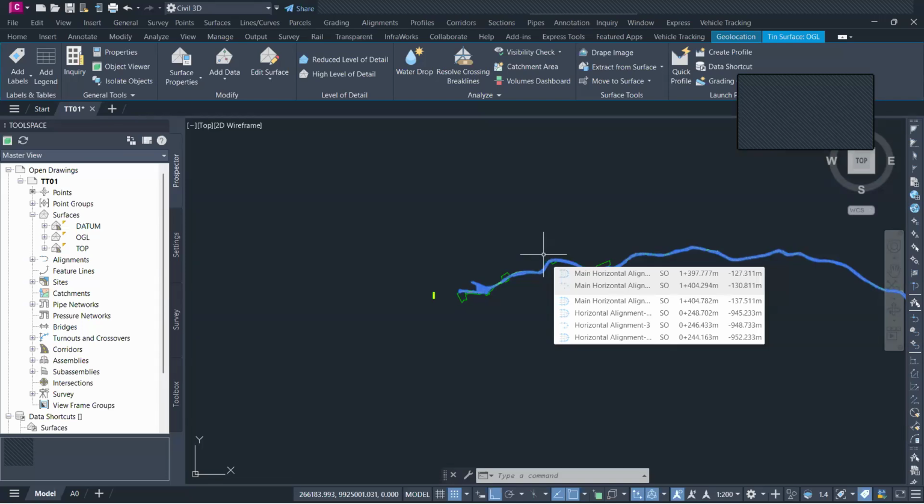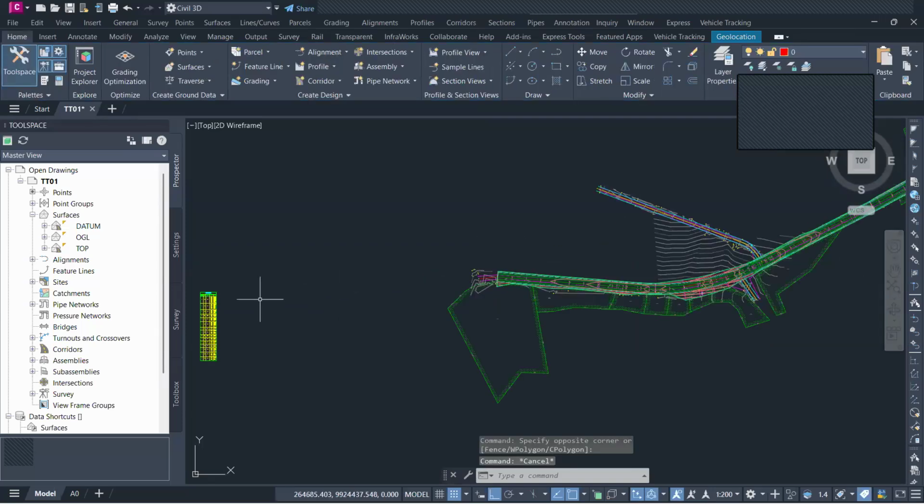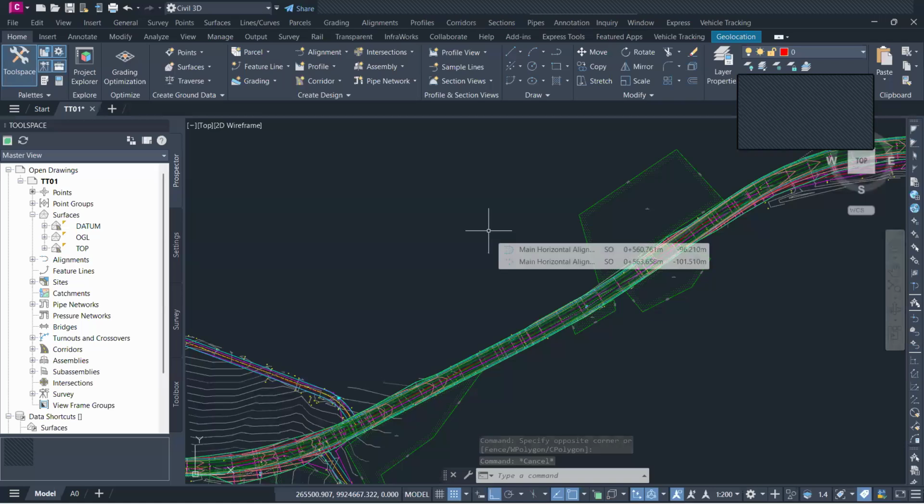So if it is a pipe culvert, you will be able to know what is the volume of the wings. You make the measurements on site, or you use the standard drawings. So using standard drawings is where we know if it is a 900 millimeter diameter culvert, we can be able to know that it needs to have wing walls of this length and all of these figures. But it is always wise for you to do such measurements on site to be accurate.